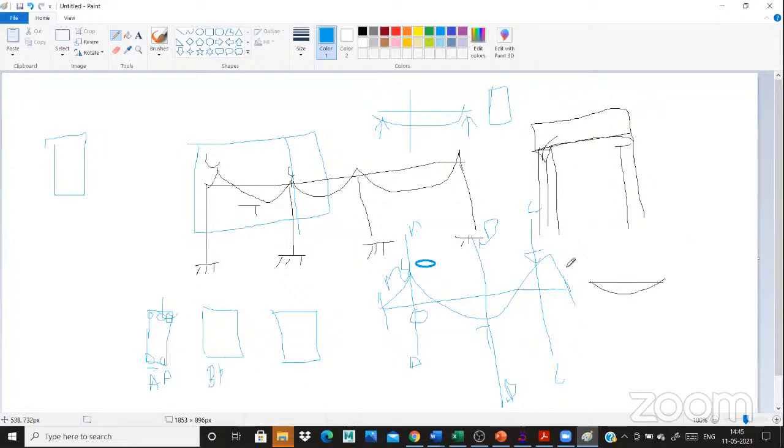That is the BB cross section. The higher rebars come under the tension zone. This is a tension zone. The moment will be high in the tension zone. The compression zone has 0 moment. Then I provide a minimum of 2 bars in the compression zone. Then I provide the higher bars in the tension zone for the mid section in continuous support. Okay. The next cross section is CC.